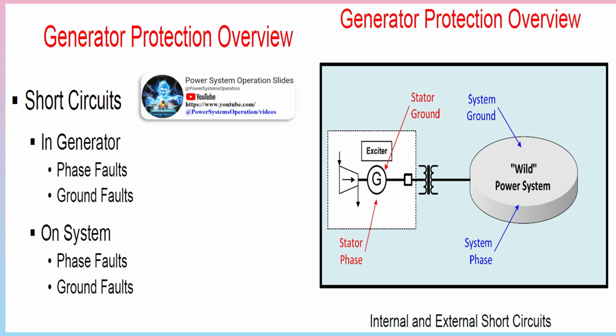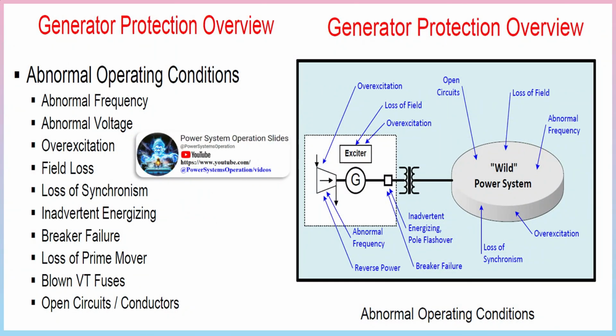Grounding techniques. The question is, why ground? It improves safety by allowing detection of faulted equipment, stops transient overvoltages, notorious in ungrounded systems, and gives the ability to detect a ground fault before a multiphase-to-ground fault evolves. If impedance is introduced, it limits ground fault current and associated damage, and provides a ground source for other system protection and other zones supplied from the generator.